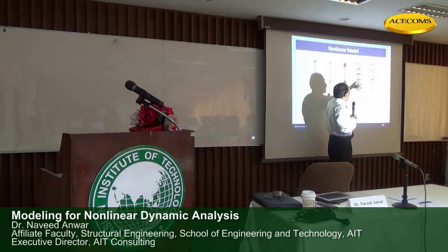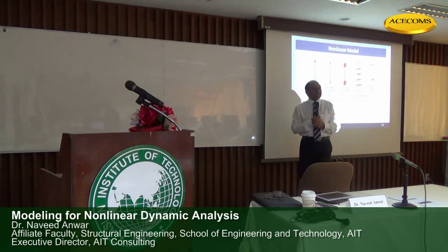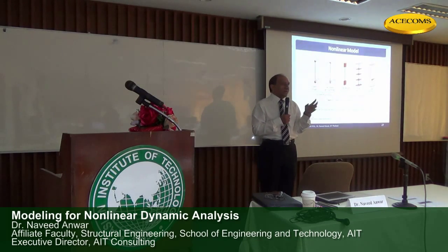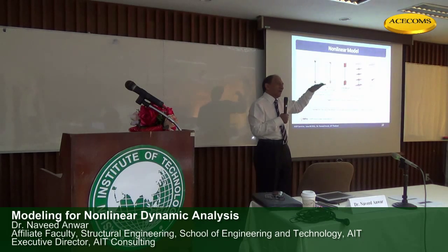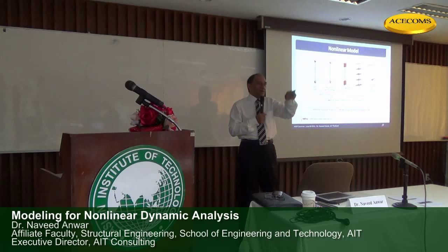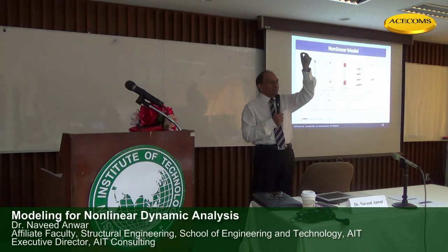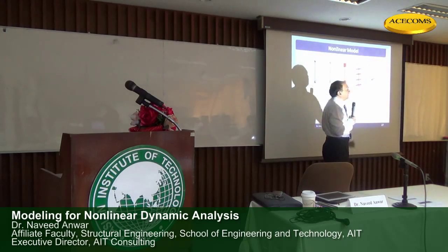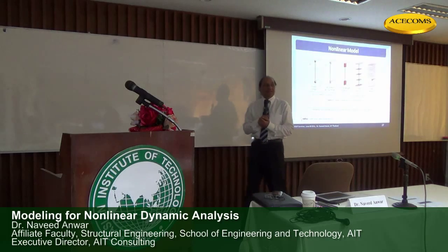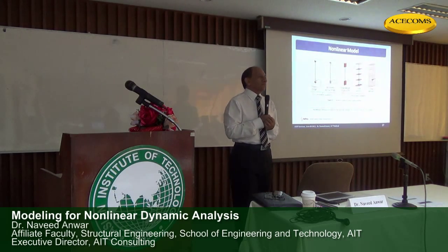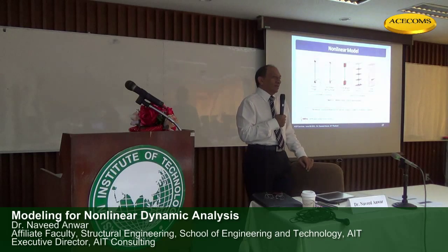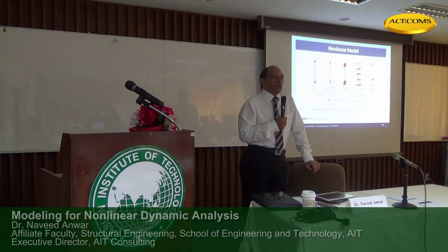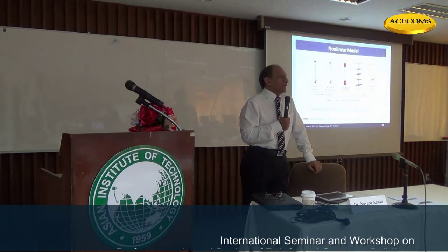Fiber section: we consider many sections to be nonlinear along the height, and they are all interconnected with each other. So unlike each hinge which is independent, fiber sections are linked to each other, and they are at the same location going through the entire member. So their nonlinearity is linked. And then finite element meshes: nonlinear finite elements. The most common of them that we are using these days is the nonlinear shell element. So you can model the entire wall or a slab to be nonlinear by putting in nonlinear shell elements.